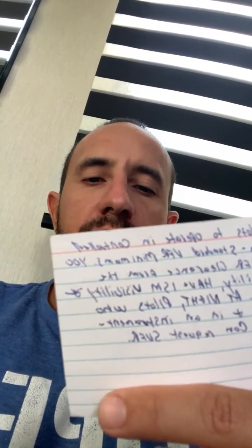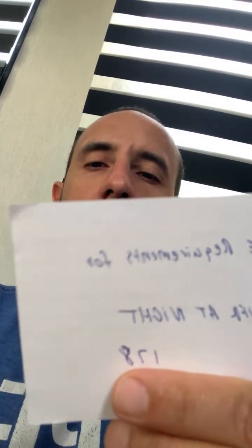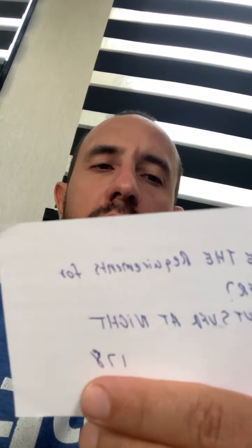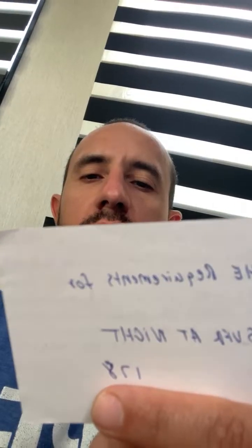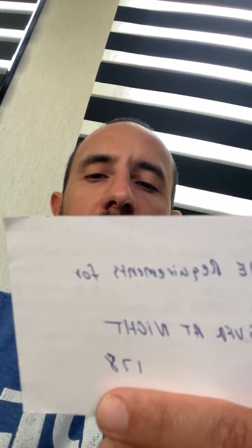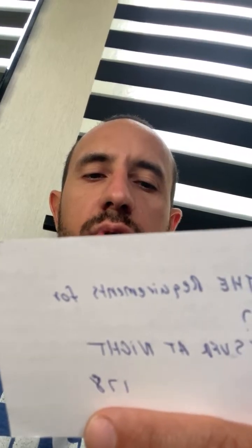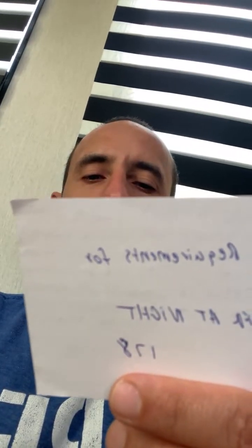What are the requirements for special VFR? What about special VFR at night? Special VFR allows pilots to operate in controlled airspace with less than standard VFR minimums. You must obtain a special VFR clearance from the controlling ATC facility, have 1 statute mile visibility, and remain clear of clouds. At night, pilots who are instrument rated and in instrument equipped aircraft can request SVFR, so you need to be IFR. 14 CFR Part 91.157.